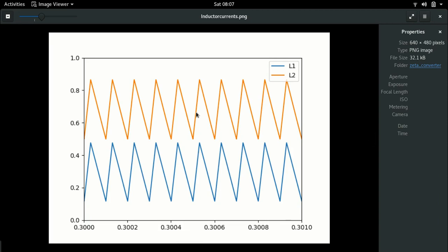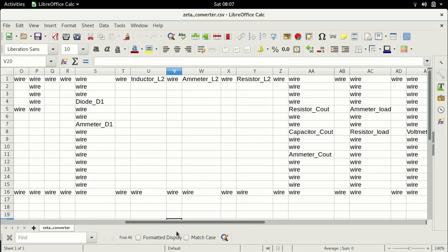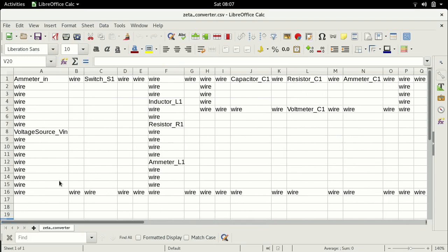The reason is because the duty ratio is low, the current through the inductor L1 is going to be lower because it is turned on for a lesser amount of time. And as you see from the circuit diagram, the lesser the amount of time the switch is turned on, the inductor current will have a lower magnitude for the simple reason that this is directly fed by the input.